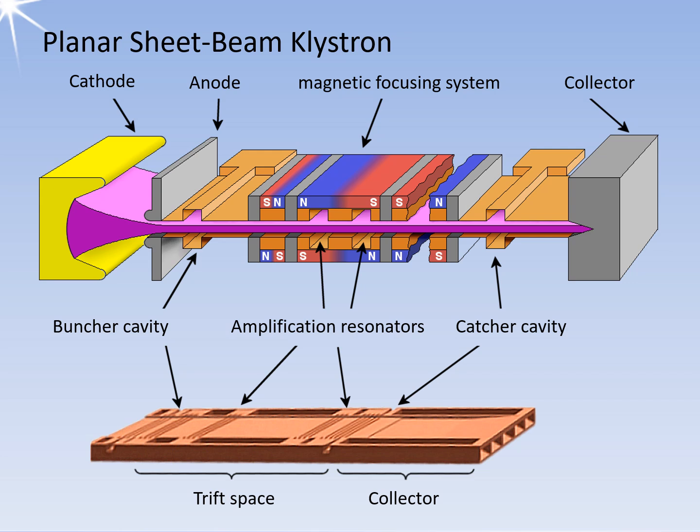The high precision required for the cavity resonators, ranging from 2 to 3 micrometers, necessitates using new manufacturing techniques typically found in the semiconductor industry. This process is known as LIGA, which stands for lithography and electroplating, in German language galvanic, and is a form of photolithography. The klystrons described so far are primarily amplifier tubes. While they can also function as oscillators with appropriate feedback, this is a complex procedure. It necessitates the connection of a high-quality frequency-determining component outside the tube. Additionally, broad tuning is generally not feasible, as each cavity resonator would need to be retuned individually.